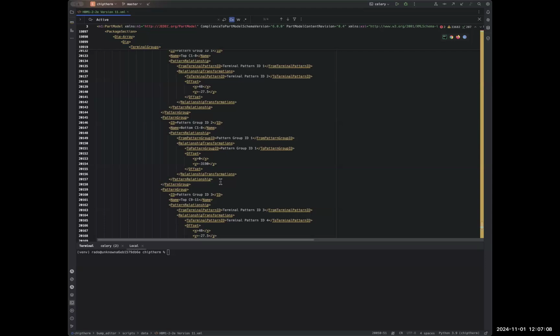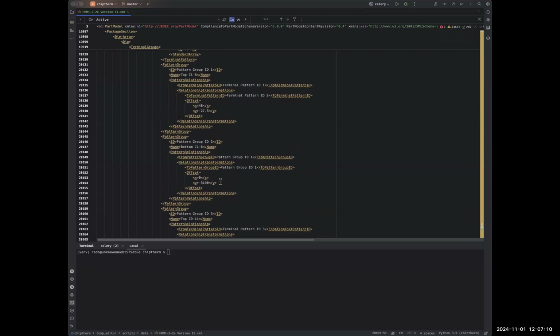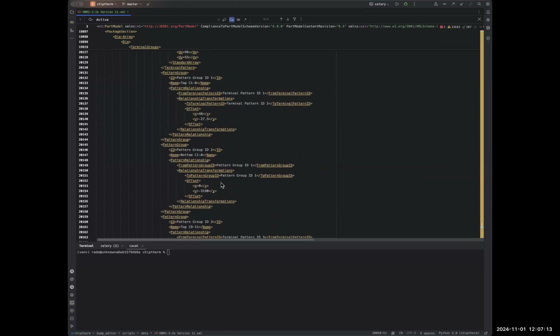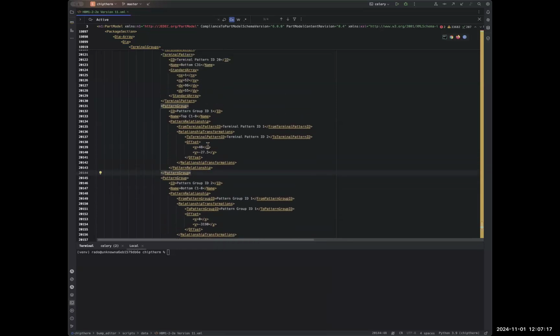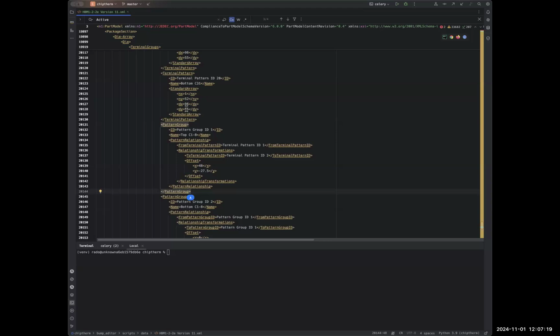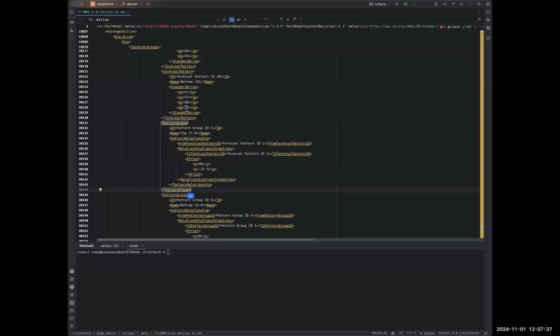I believe that the DX and the DY is basically two terminals apart, because that's how we did the pattern groups themselves. They're basically offset, alternating. So the actual difference of every single terminal in the X direction would be half of 96, and half of 55 in the Y direction.